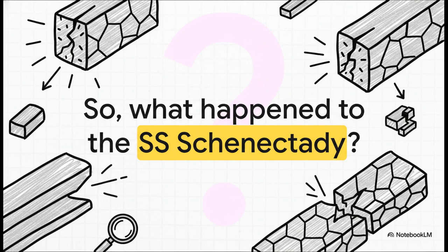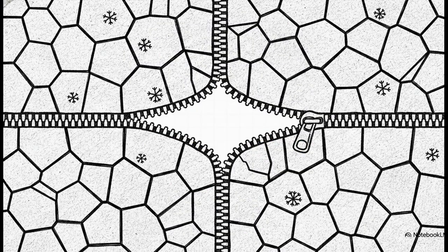After the failure, investigators took a close look at the steel, and all the evidence pointed to something called intergranular fracture. On that very, very cold day, the steel's microstructure became brittle. And those grain boundaries, the very same regions that normally provide strength, they suddenly became a path of weakness. A crack formed and just unzipped the ship right along those microscopic seams.